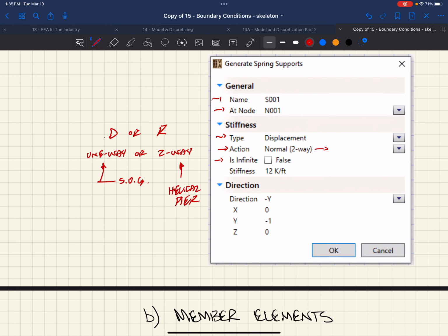You can batter the helical piers. That means you drive them in at an angle. That'll give you some lateral support, right? Because if you drove in all of these screws vertically, right, now all of a sudden there's no lateral restraint at the top that interfaces the structure to the soil. And so a lot of times you batter some of those piles to make that work.